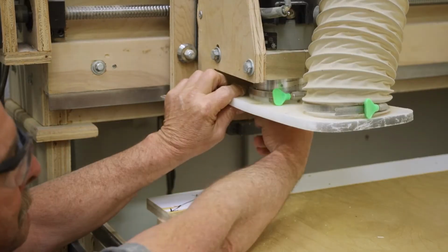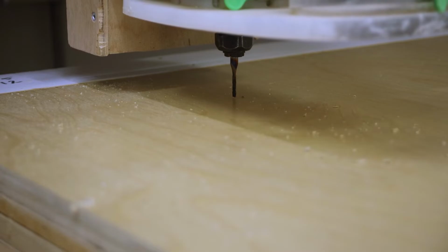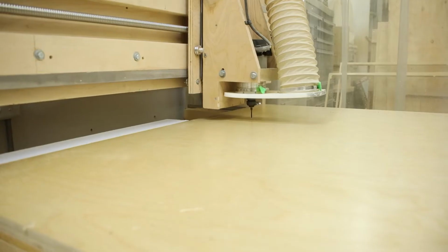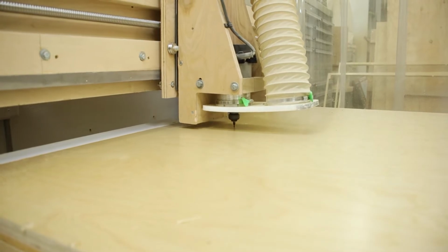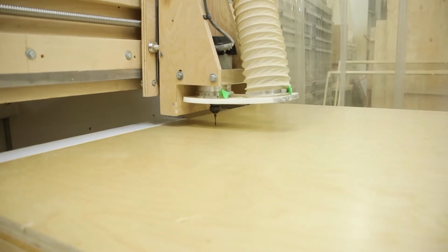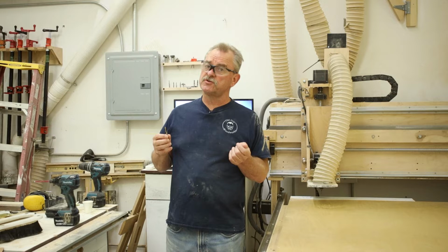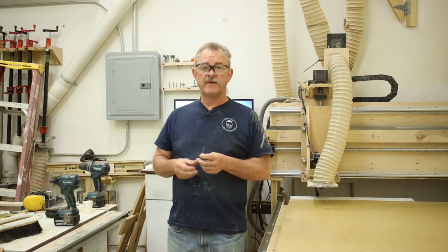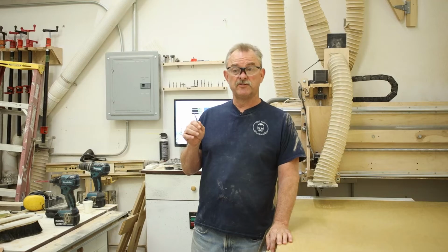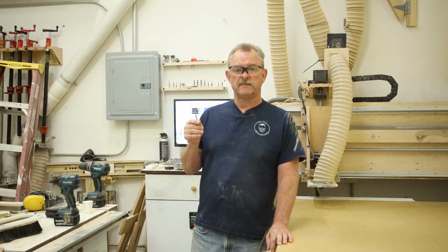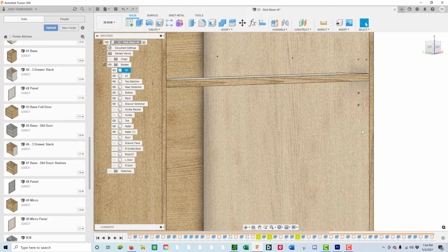And I just go ahead and attach that 1/8 inch, and I manually set the height because the depth is not important when you're just doing screw holes and little peck marks for drawer guides. Once I have all the 1/8 inch holes pre-drilled, I come back and I use this 5mm end mill to pre-drill all the shelf holes and hinge plates. And I lay all those out.